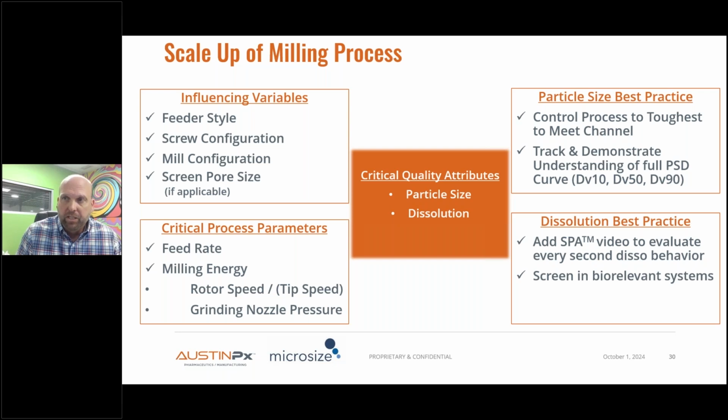And then additionally, mill configuration, as we talked about those different technologies. Once the technology is selected, then optimizing and holding constant that configuration. And that can be certainly mill size and chamber volume and nozzle angle, but it may even be as minute as things of the venturi that helps feed the material into a given jet mill, or the screen size that's present in a mechanical mill.